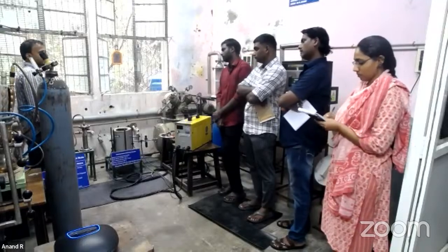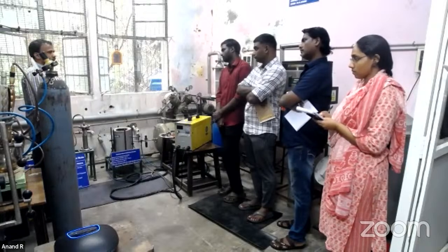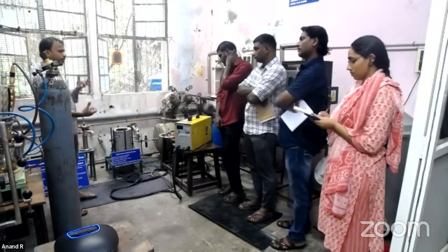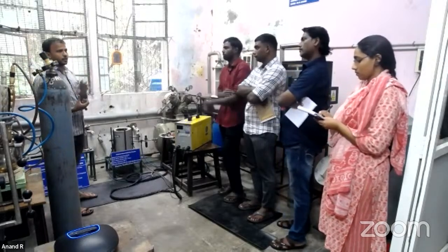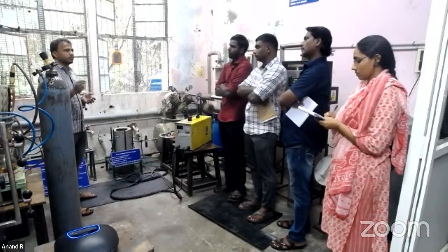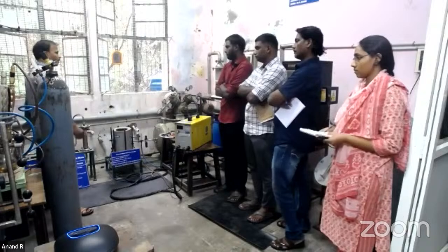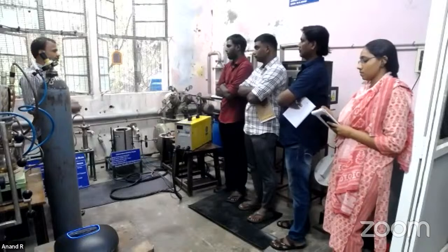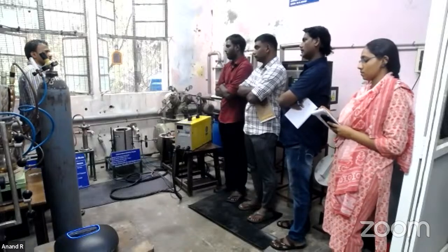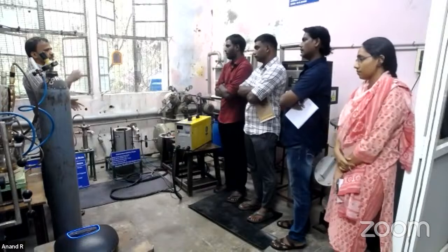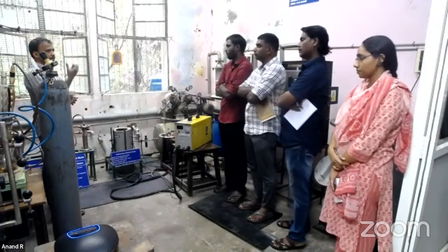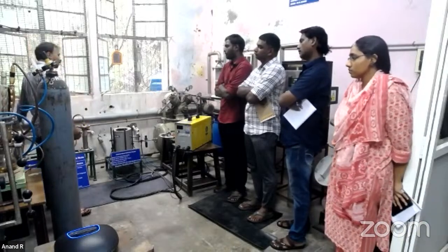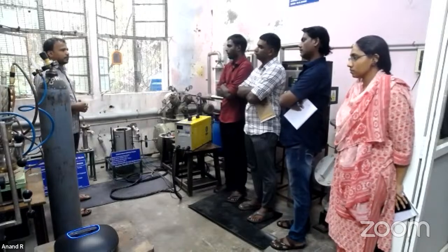Then this is the mist eliminator. Why are we using a mist eliminator? Because this is direct scrubbing, so water is directly meeting the syngas. If water directly meets it, the syngas may capture moisture or carry some quantity of water. That water will affect the calorific value of the syngas, so we could not utilize it for further application. So we are using a mist eliminator. It has a porous structure, like a jet. It will condense the water present in the syngas, it will drain down, and then we can get clean syngas. That may be a combustible fuel.